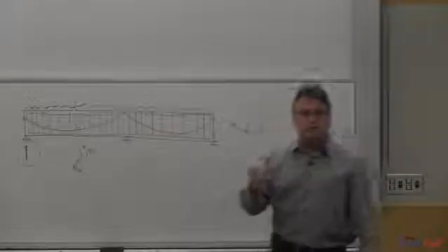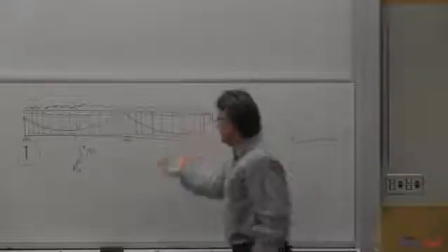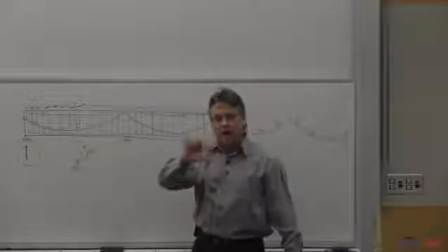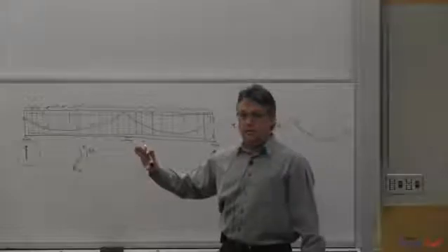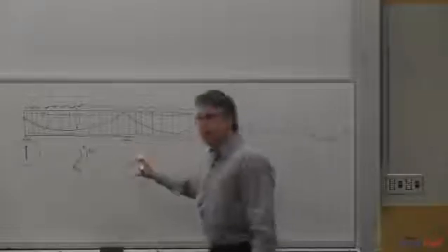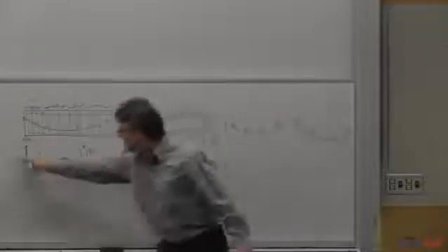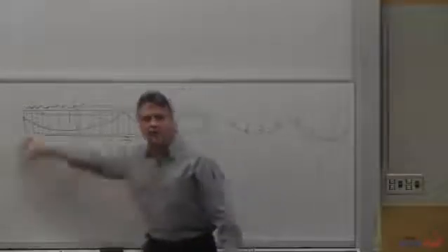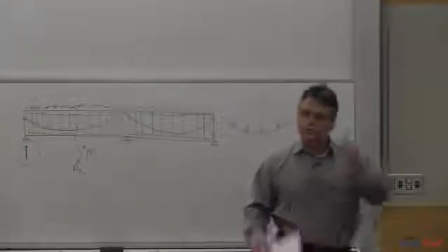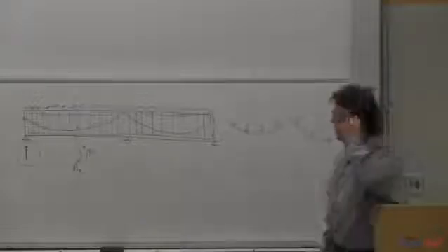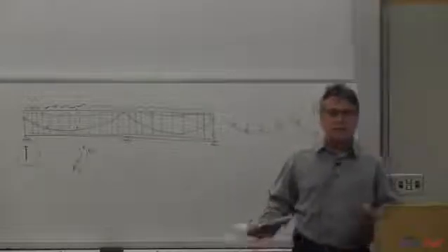So in your homework number 2, you did both, and you should have proven to yourself that you can take the equivalent loads from the tendons, put them on the concrete, and get a concrete-only shear and moment diagram that's not real. It's just what the concrete thinks is happening. And if you use those moments, you end up getting the same exact stresses that you got using the much more complicated method that had everything in there and the real reactions. Just look at your homework number 2. It was simple, and the problem is I think I give some simple homework and it doesn't look like it's that theoretically complicated, but they really are.